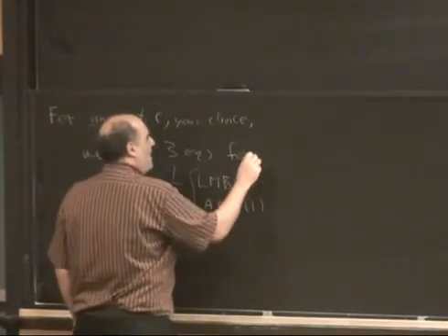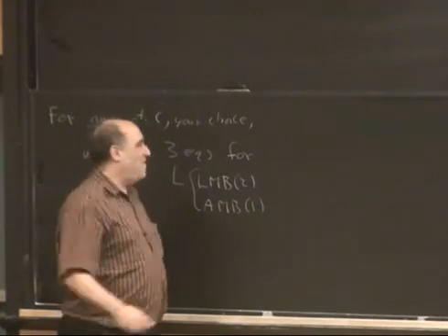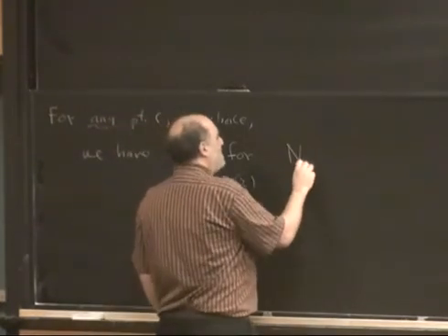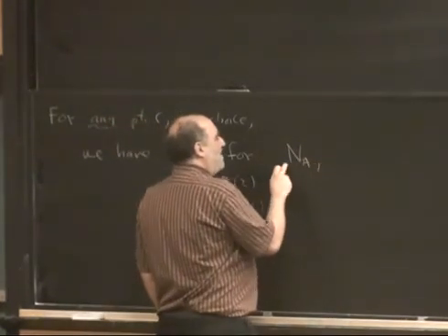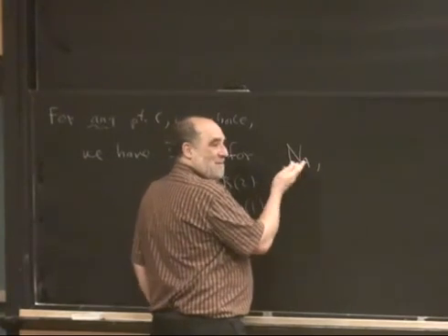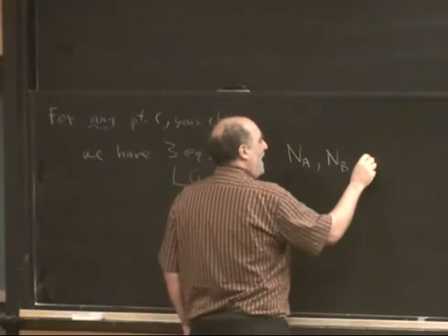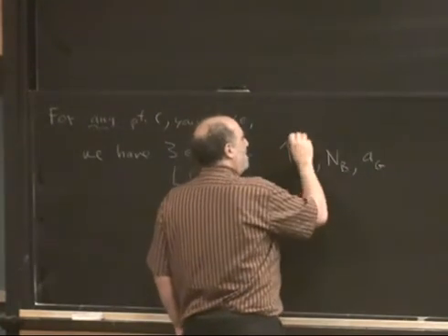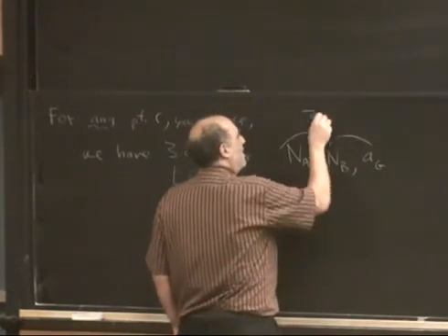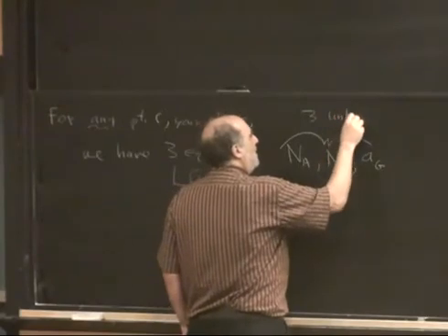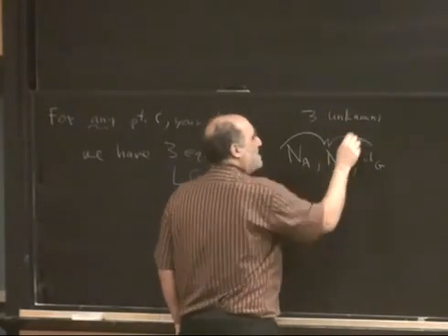And then how many unknowns do we have? We have the reaction at A. We could say mu times N_A, but we know what that is because we know what mu is. We have the reaction at B, and we have the acceleration of G. So we have 3 unknowns. So we have 3 equations and 3 unknowns.